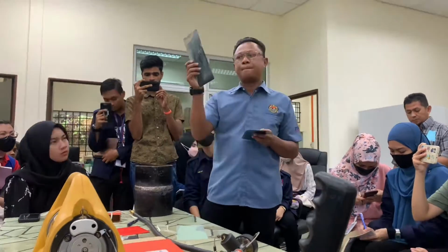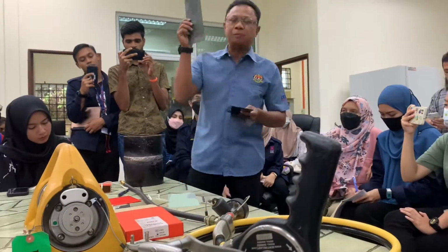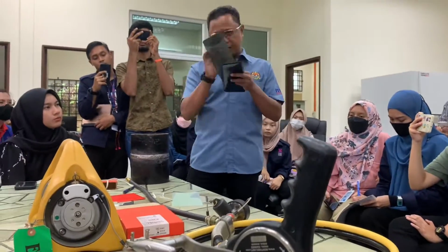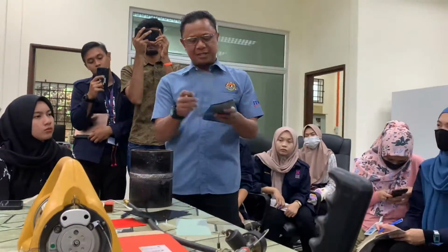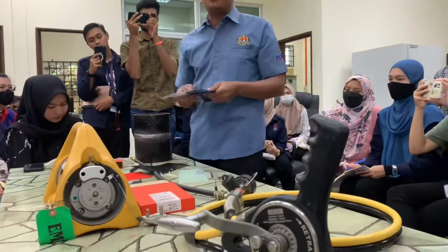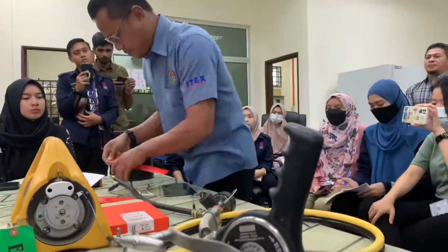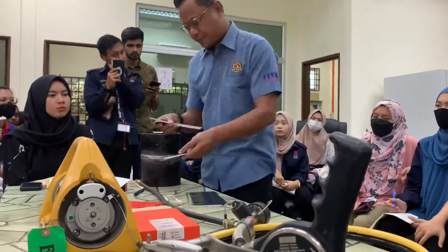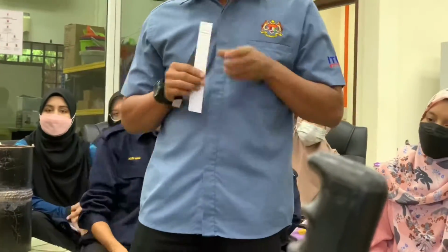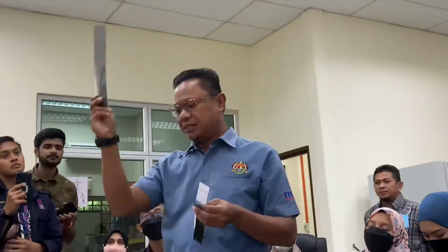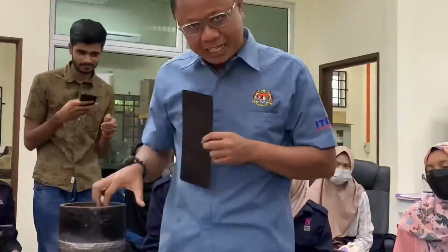The film or an electronic device records the amount of radiation that reaches the film through the test specimen, known as a radiograph. By studying the radiograph data, defects can easily be recognized. If the material is found without any defect, the entire ray will evenly pass through the material. But for material containing a flaw, the ray passing through the flaw will get absorbed to a small extent due to change in density.